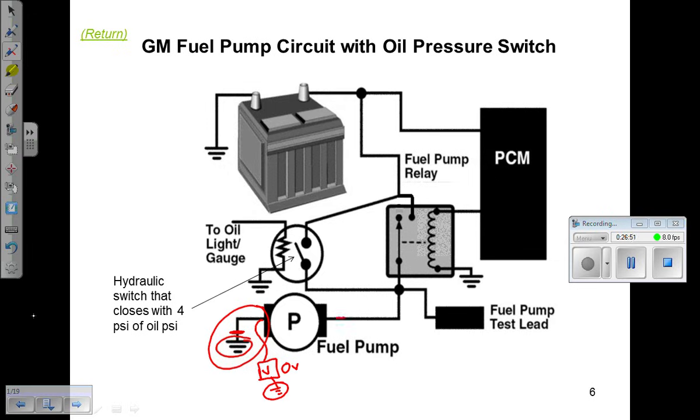If the circuit's loaded, that means you have 12 volts coming in this way. If you have 12 volts here, now your voltmeter is actually going to read 12 volts right here with a bad ground. You will read 12 volts right there. The key was the circuit had to be loaded. You cannot check this ground accurately with a voltmeter unless you have power feed coming in here.